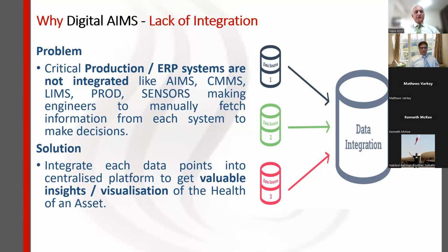A good example would be if you've done an FFS, and the FFS assessments have told you that you've got to derate your system, well, your operating envelope has reduced now, and you need to track that through your production PI system, whatever you have, get those data, laboratory information management system data, and then put it through what they call an integrity operating window limits.